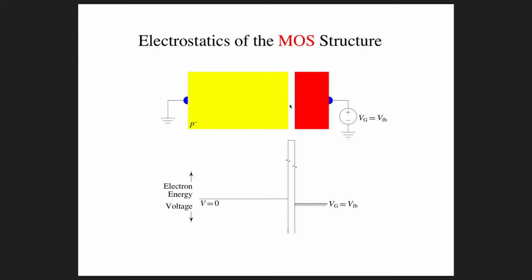And that's really one of the beauties of silicon, and that's why it came to be the main semiconductor material that we deal with in modern electronics. And then you have the silicon, which is down here. I mentioned that this electrode is usually called the gate, the M, and this part of the structure, which is the silicon, is typically called the body or the bulk. Okay, sometimes the substrate.